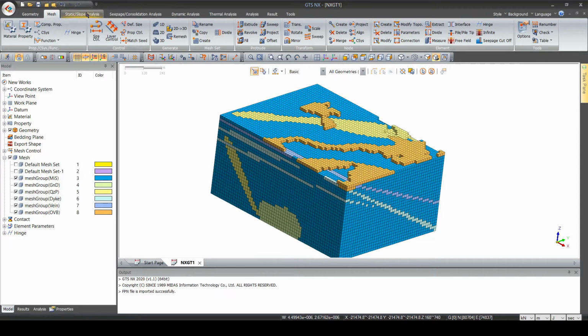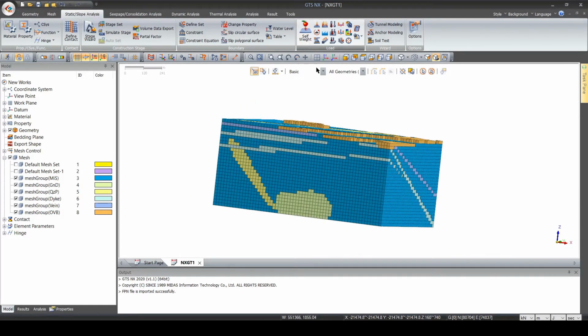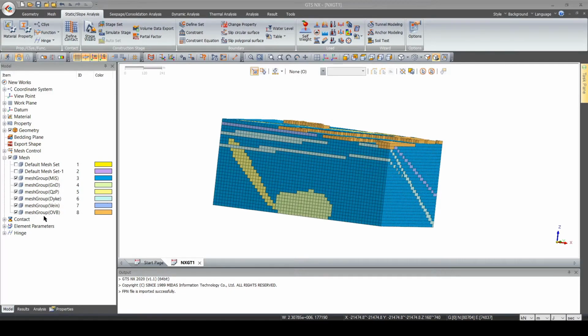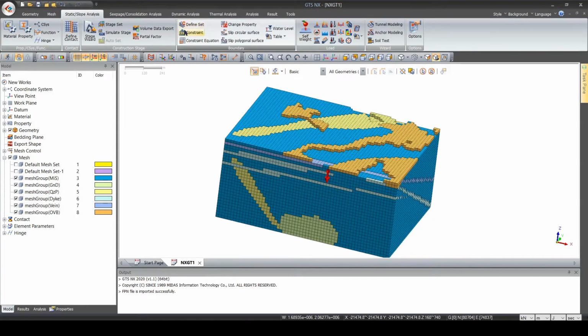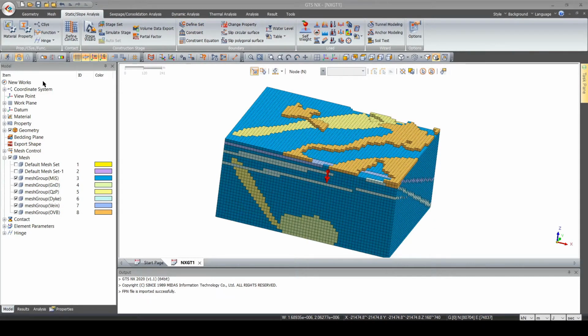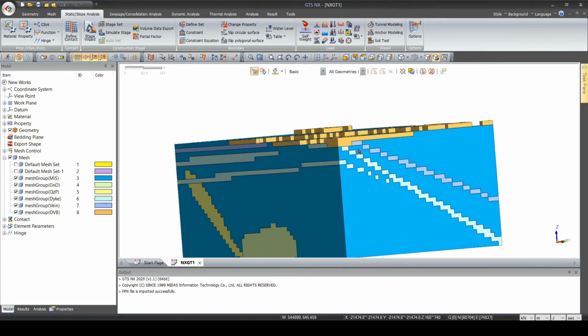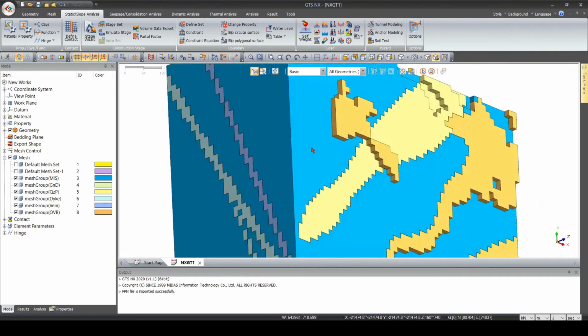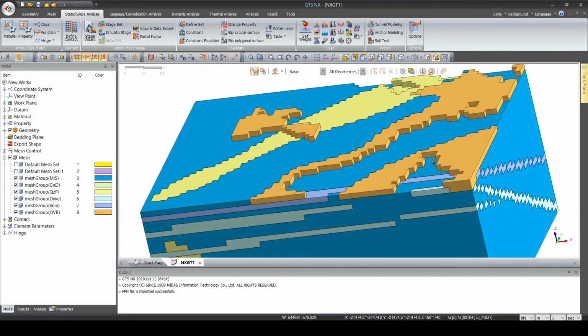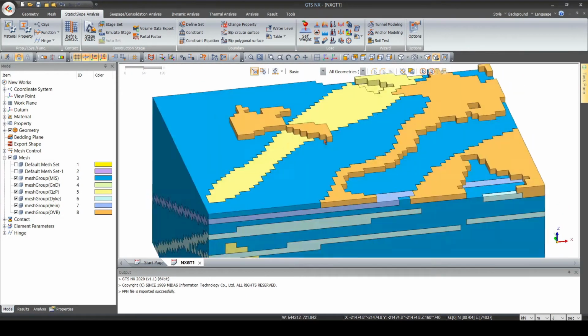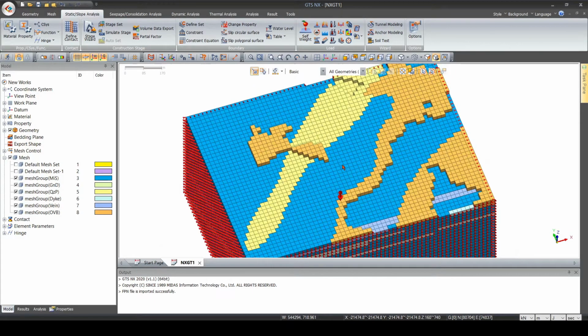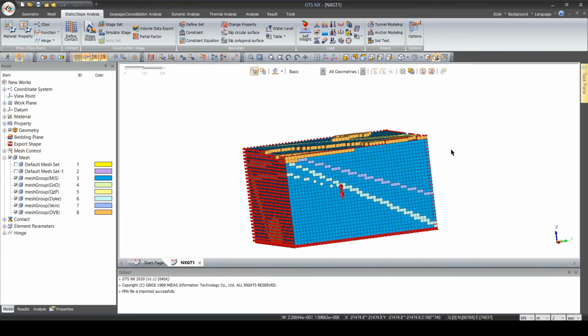So now the model is completely ready to be modeled. In fact, if we go to static slope analysis, we can set self-weight, and we can set the constraints, the boundary conditions. We put auto. Here we are ready to simulate. If we have some lithology with a certain name, we can deactivate mesh sets, and that's it.